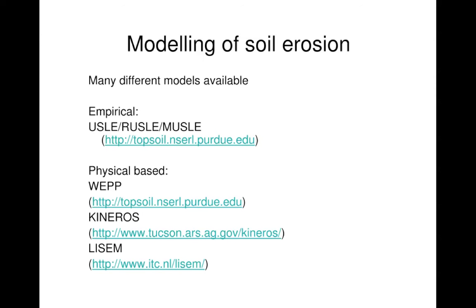We'll come to them in a sec, but USLE and RUSLE look at things like the erosivity of rainfall, and they have a parameter for that. Then you multiply that parameter by another parameter which represents the soil type or soil texture. Then you multiply that by another parameter, and that might represent the slope. Multiplying all these empirical numbers together, you end up with an index for how erodible your soil is. And you can see there's going to be problems in there if those equations in USLE and RUSLE have been